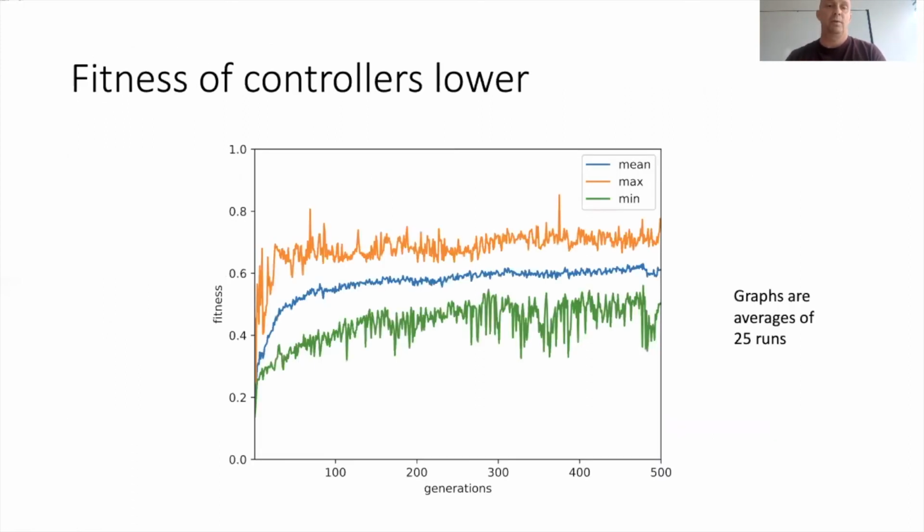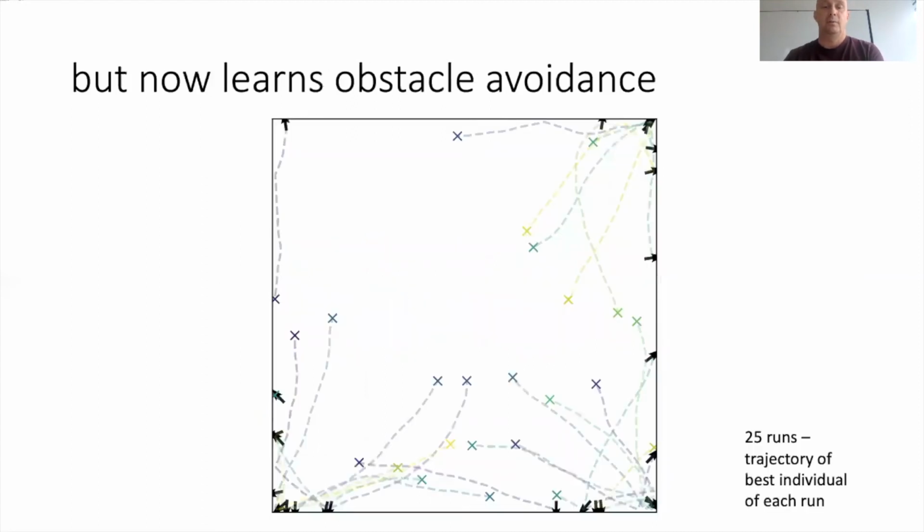And we actually see this. When we run the evolutionary algorithm, we can see that the system converges, of course, at a lower level, because now we have a co-evolutionary pressure that makes the configuration as hard as possible for the controllers to solve. And when we see the same graph again, the black arrows are the starting positions. Here it's clear that the evolutionary process has put the starting position close to the wall, because that's the most difficult for the controllers. But the controllers learn to deal with it. We can see that the robots often start close to the wall, for instance, down here, but then learn to back away and end up away from the wall. There are a few failures like here, maybe a few more, but in general, the solutions are found.